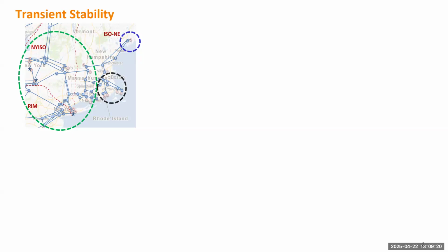For the interarea modes, you will be able to see a group of generators oscillating against another group, maybe the rest of the system. So it's totally fine if you see coherent groups of generators, some generators tend to become closer to each other, but some will have a different phase. As long as over time the generators stay together closely around the same frequency, we still consider the condition a stable condition in terms of transient stability.